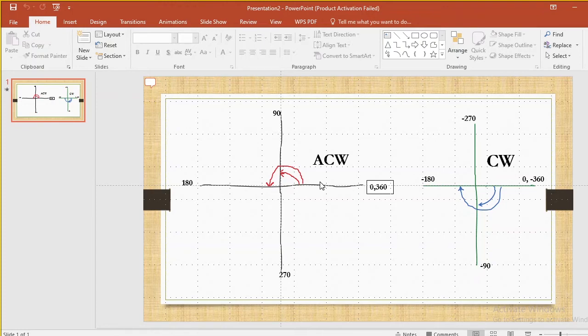This is a Cartesian plane. We all know that right from primary school. So how does AutoCAD make its own angle? Like, which direction does it say is positive, is negative? Looking at this, when you select line in AutoCAD, primarily the angle is at 0 degree when you place it in a horizontal direction, that is placing it in this particular direction, the horizontal part that is going in this direction.